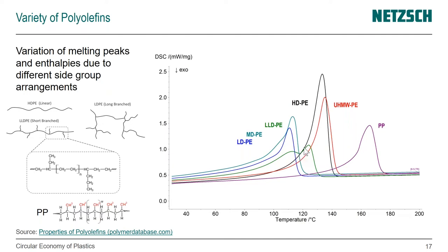If we do peak separation and we don't know that it's LLDPE and we can't tell it that the shape should be similar to this, we would very likely create a new peak-separated curve that looks like this green one and goes down here, and you see we would underestimate the enthalpy based on that.